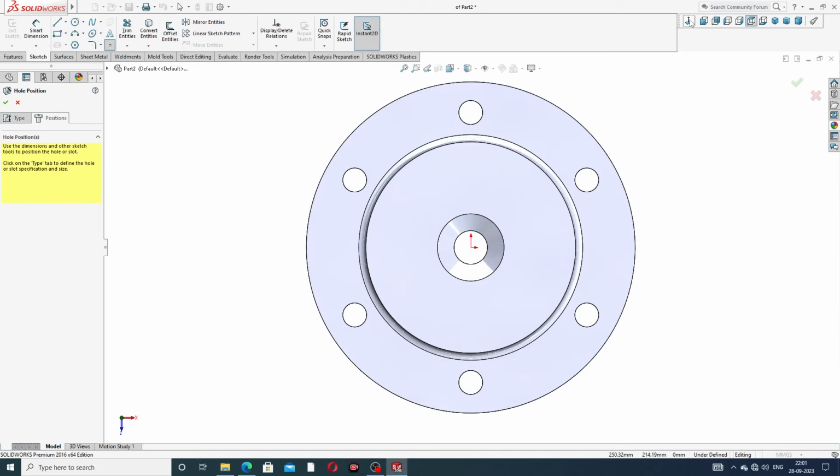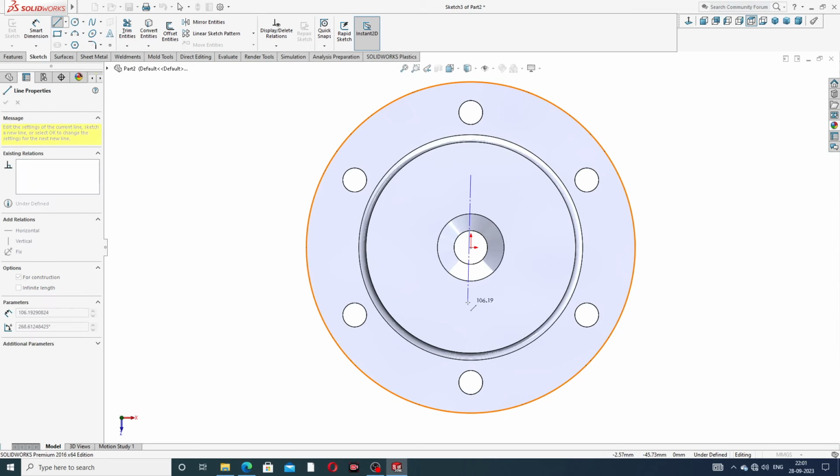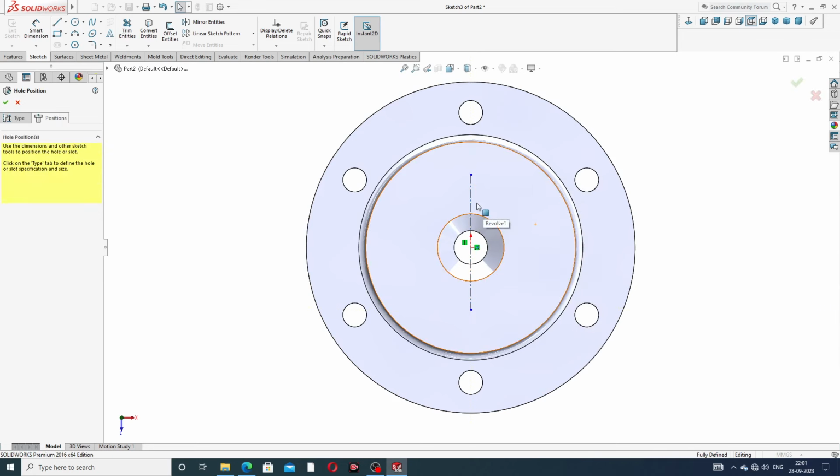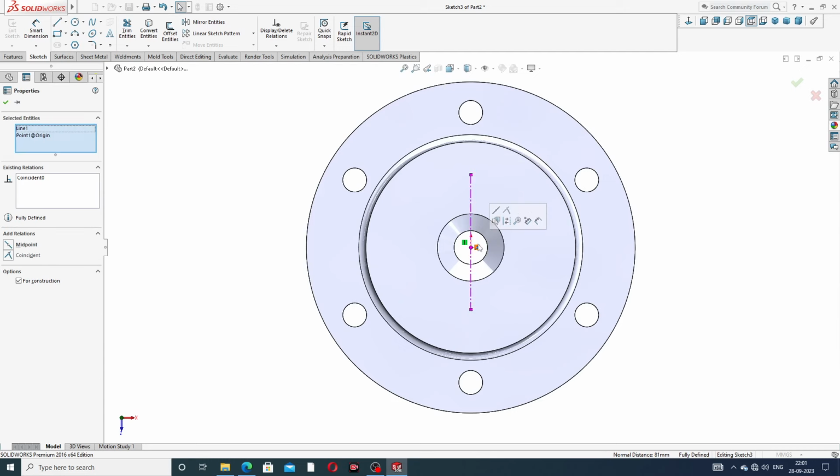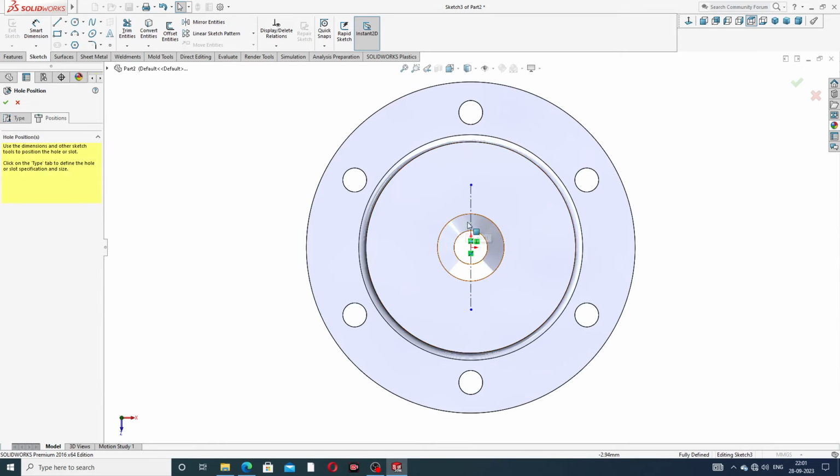And going to position, and this is sketch normal. Okay, and drawing a reference line. The reference line is perfectly drawn here because this uses a mid plane. Select this line, press the control button and select this point, and use mid plane. All is perfect, and the dimension is mentioned here.